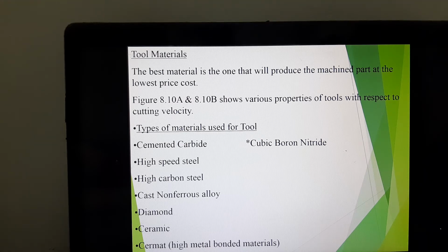However, if it's affordable, the best compatible cutting tool would be diamond. A diamond cutting tool is going to be your best bet. Why? Diamond is the hardest cutting tool material, or hardest material available. It's chemically inert, which means it will not react chemically, and it can cut all the materials including another diamond.